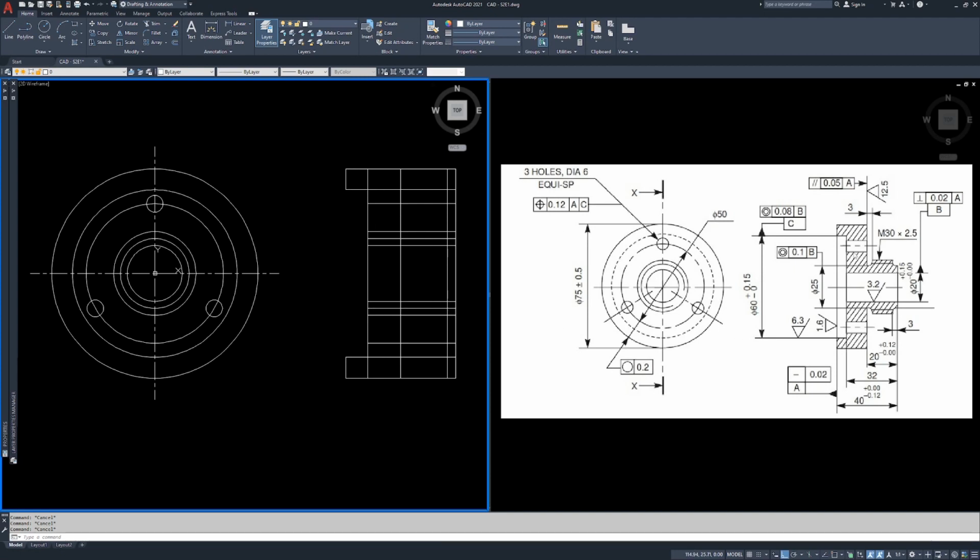So right now we have this top piece and we have this open in here, even though there's an edge back here. You know what? Let's just draw that edge back in while we're here. Endpoint, endpoint, done. So that's this area here. Now what we want to do is we want to trim out all this stuff back here because it doesn't exist. So let's use the trim command, TR, and let's just window the top three and the bottom three lines.